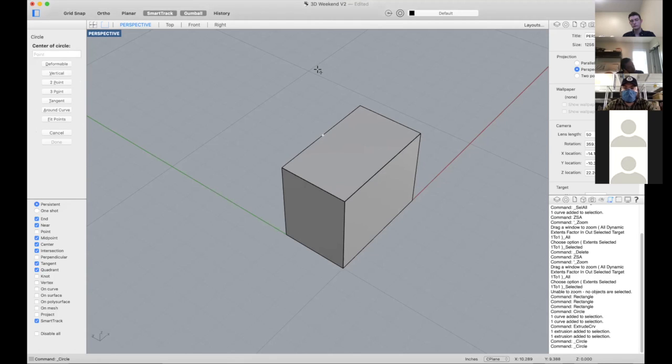To make that dot go away, I hover over it again. That white dot is now a reference point, and it will create lines based on that reference point. So let's say I want to be in the middle of this line and the middle of this line, and I want to find the point between those two lines. There you go. You highlight the middle, and you get the middle. So now that is the middle of my circle.